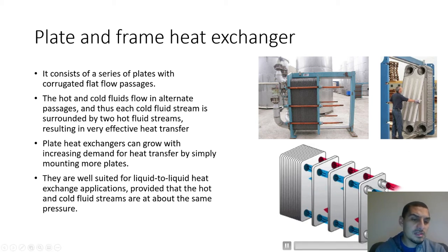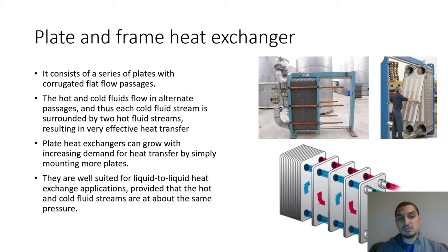And the way it works is that we have a hot fluid flowing between the two plates, and then a cold fluid between the next two plates, and then a hot and then a cold fluid, then cold and hot, and so on. So each fluid is transferring heat with the two fluids on the two sides of the plate that this fluid is contacting, and that's why it's very compact and very efficient heat transfer equipment.